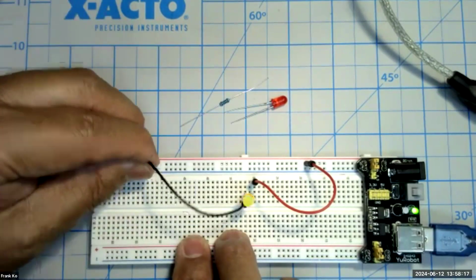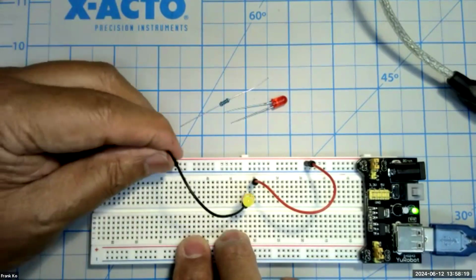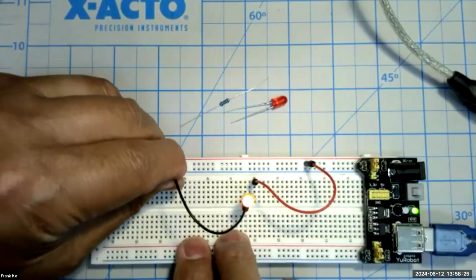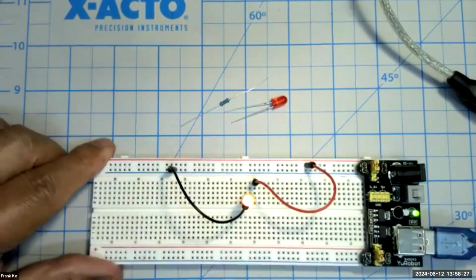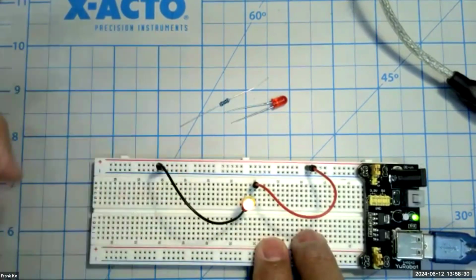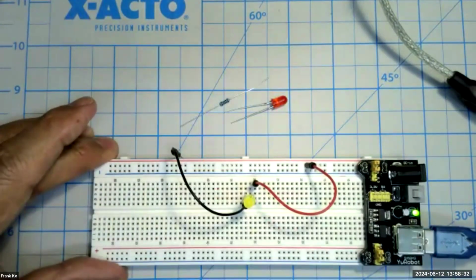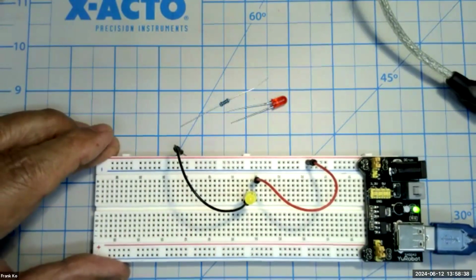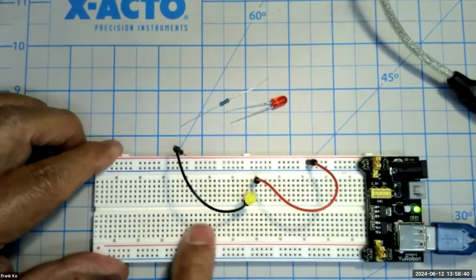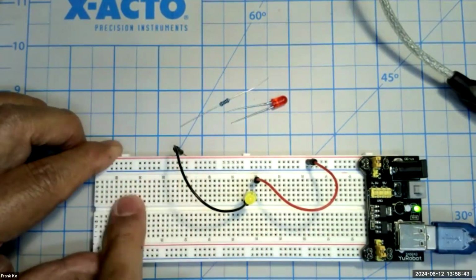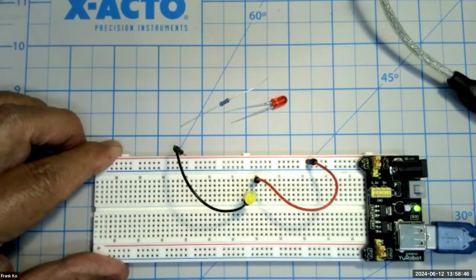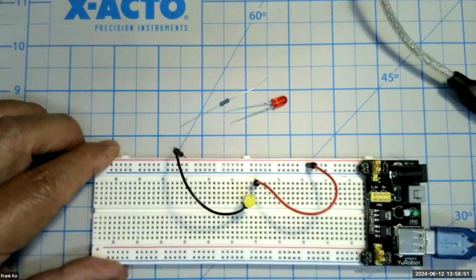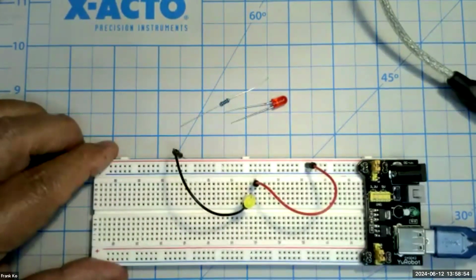So what am I doing? I am frogging my wire, simply taking the end and moving it to another location, which should ensure me the same result, even though the one right next to it may be fussy. All right, so that's a technique known as frogging. I thank my colleague from Down Under for pointing out that there may be some inconsistencies with the breadboards because of their budget, or also because of some possible factory contaminants that may have lodged into any of these pinholes. Turn this guy off when we're done, and let's go ahead and do the next test.